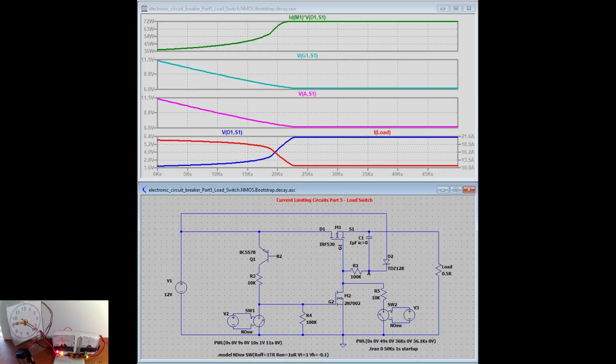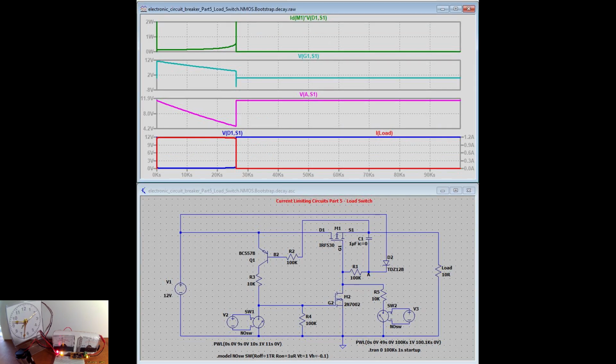The absence of the switching circuit, charge pump, to keep the capacitor charged, allows the capacitor to decay over time, reaching a point where the gate-to-source voltage is just enough to keep the MOSFET on, cyan line, with a high drain-to-source voltage, blue line, resulting in heat dissipation and power loss, green line. 2. That is why transistor Q1 is there.